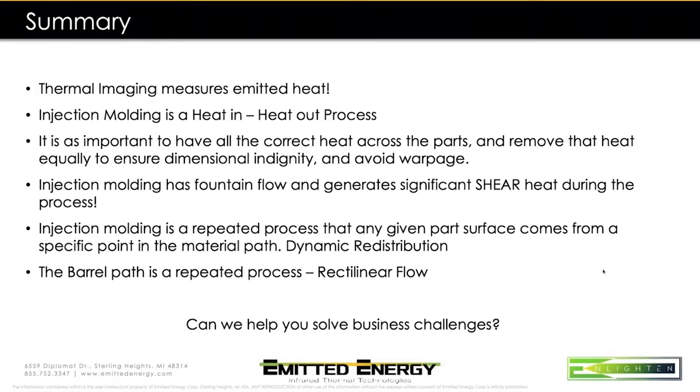Injection molding has fountain flow, which generates a significant amount of shear heat in your process. And you always have to be aware, when you design your part, of how long your shear lengths are going to be and what kind of shear stress they're going to give you. I know a lot of people use Moldflow. I use that as well. That's a good indicator of what's going on as far as looking at your shear stress.